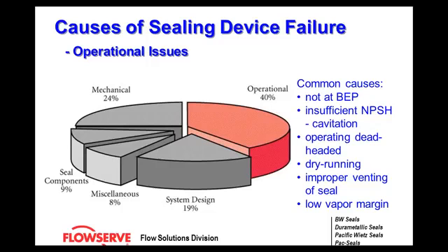Lastly, low vapor margin. These are flashing fluids. Generally, hot hydrocarbons will flash in atmospheric conditions. So as the fluid film passes across the mechanical seal, it can flash at the atmospheric side and cause a failure. Another area that's probably more common in the state would be boiler feed situations where you have hot water at 250 or 280 degrees. That will also give you a flashing situation.